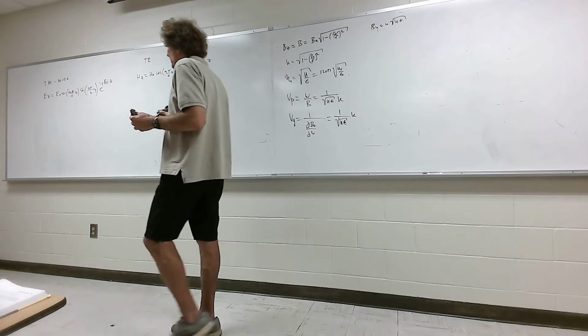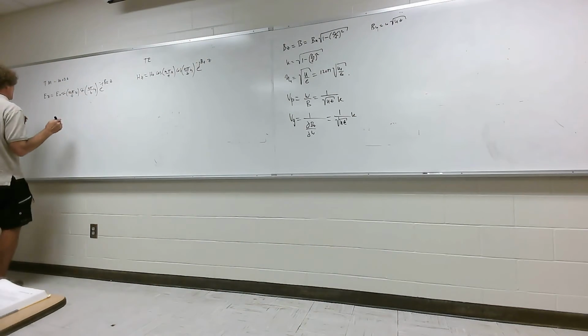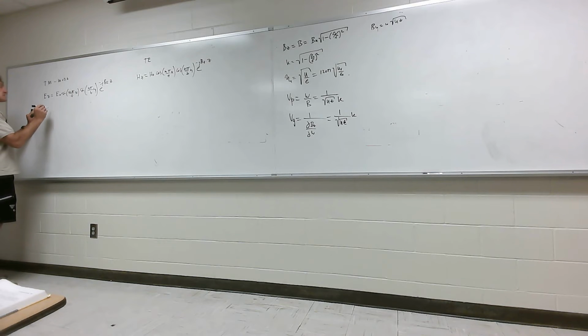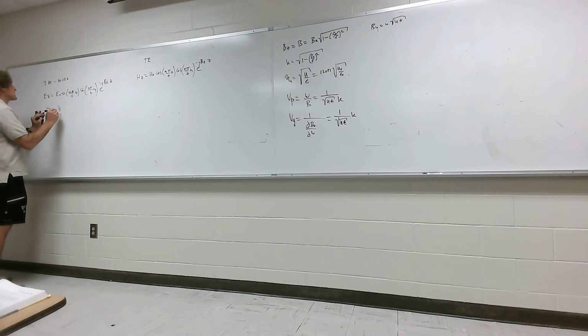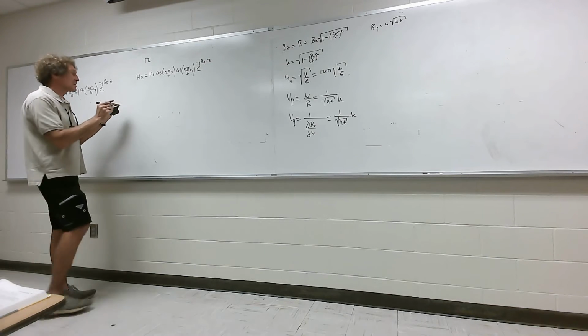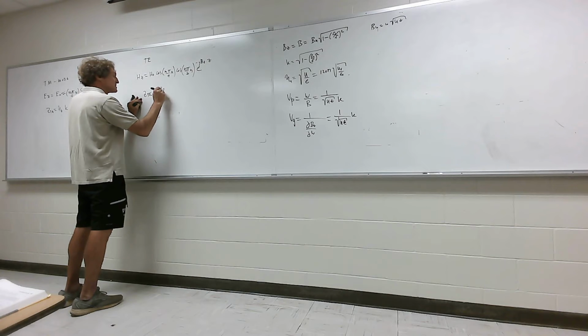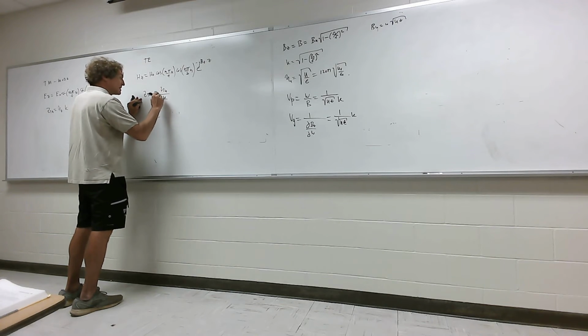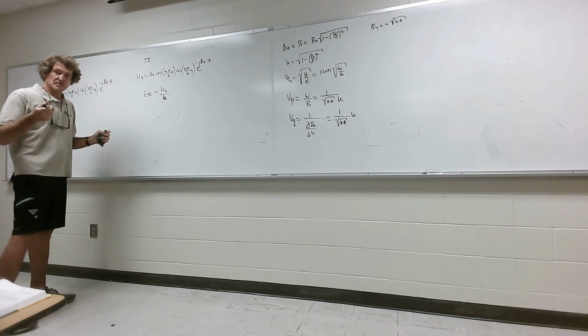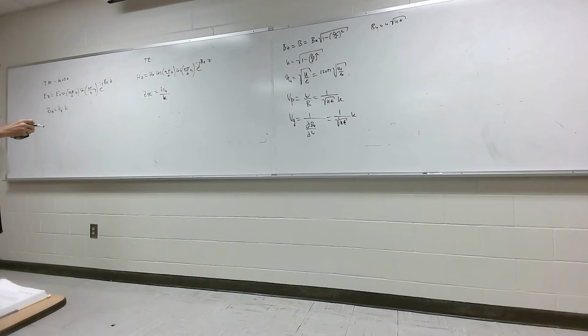Now over here, for the TM mode, the characteristic impedance, Z_TM, is equal to simply beta unguided times k. And over here, for Z_TE, that's equal to beta unguided over k. That's shown correctly in that last equation I gave you. Got the group and phase velocity, beta_z.